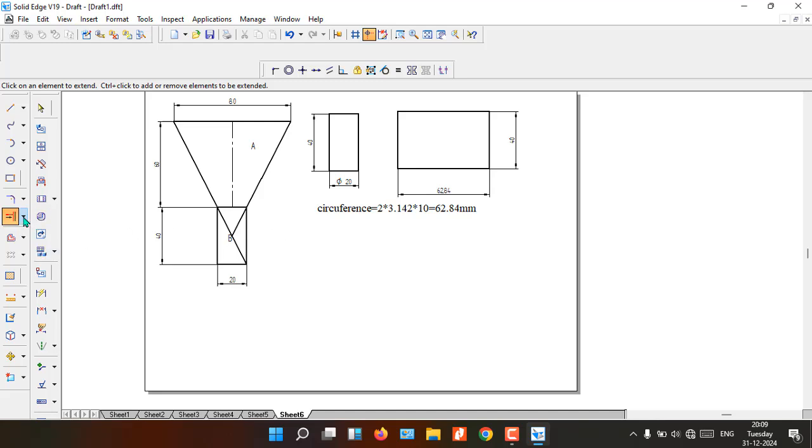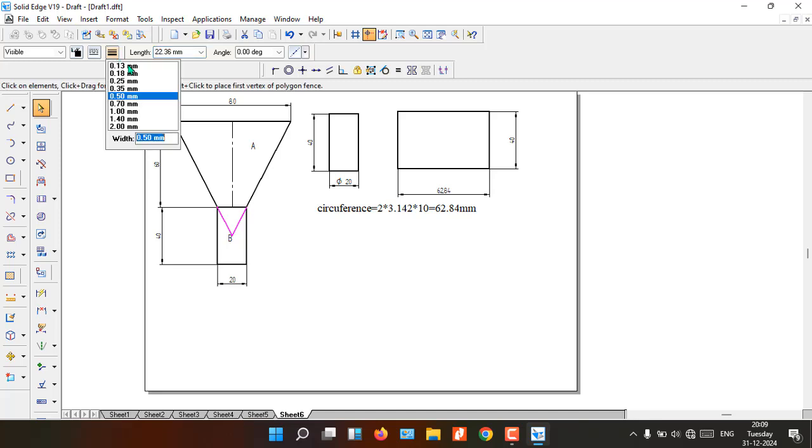So now you can see the part A as a cone. Okay, now go to the split command. So this much we are going to take as a reference. We just split those things and make those tip of the cone as thin lines.